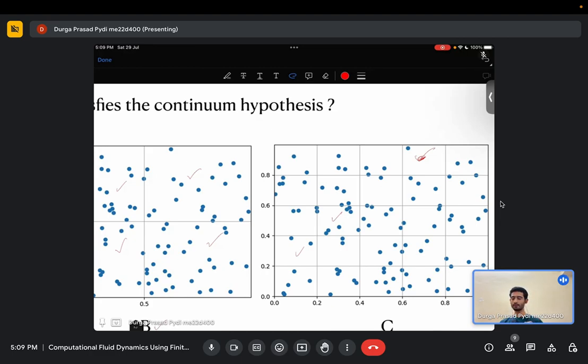So why are we bothering about this continuity? It is because we are trying to model our fluid using differential equations, and all those equations are valid only when you have continuous functions. The function needs to be continuous throughout. In this particular case, you have around 3 particles on one side and only 1 particle on the other, and the function cannot be continuous across this boundary. So we should be taking a length scale much larger than this.